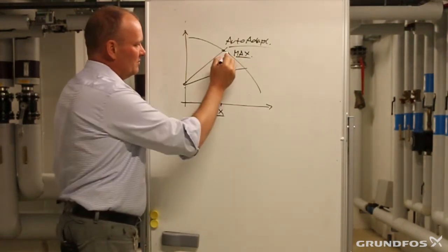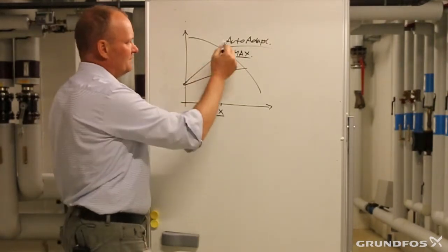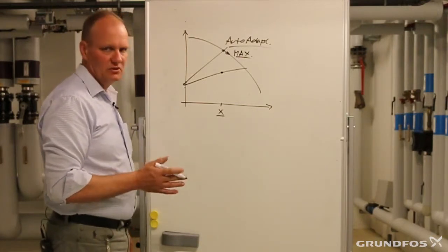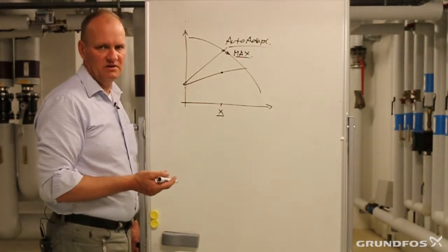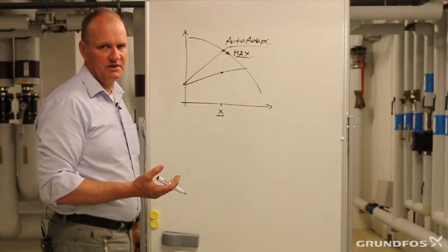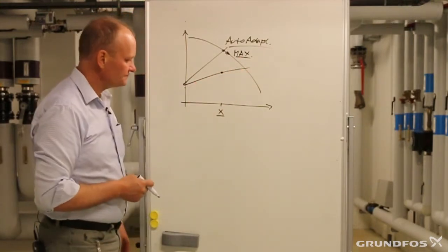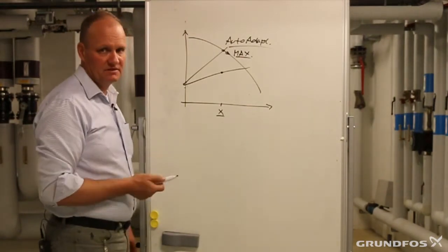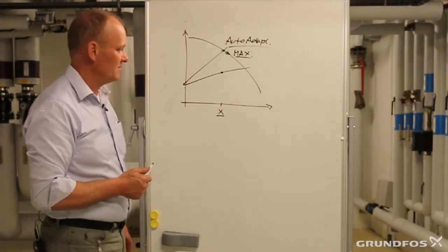So please remember that if a pump is heavily oversized, the auto-adapt function will really not kick in. So in those cases where you think that you have an idea about what the requirements are in terms of pressure, then you could choose to use proportional pressure instead, and then go up front with a lower curve. But that is where we can utilize the auto-adapt in these situations where we don't know anything about the maximum pressure loss in the system.